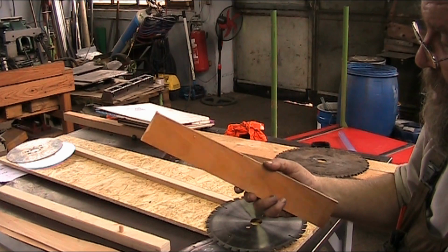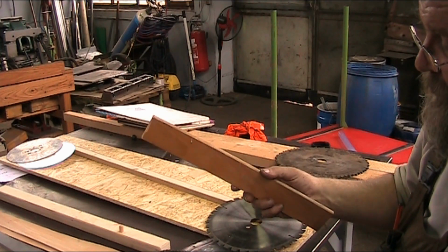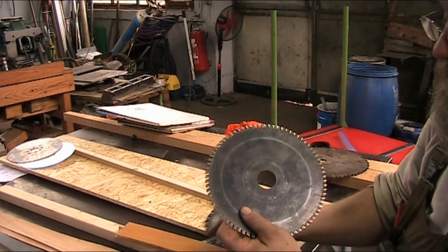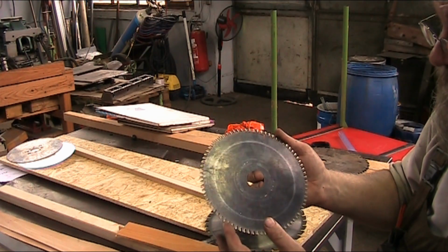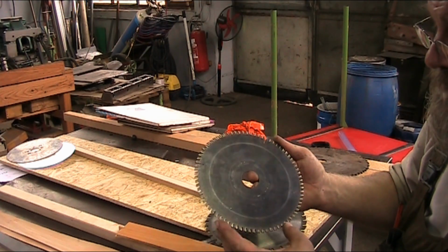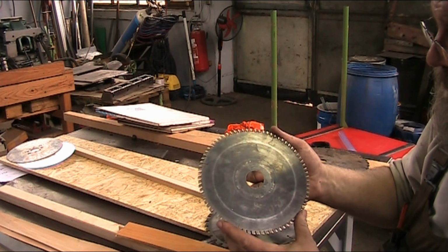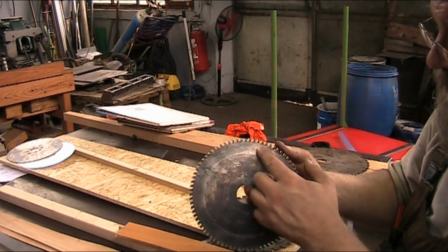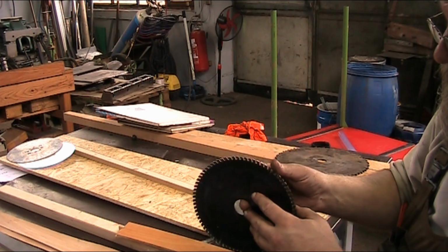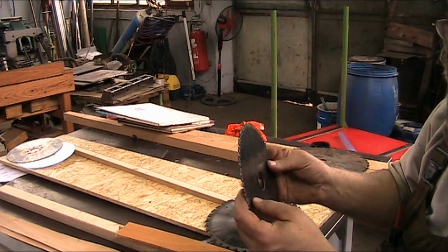So this is a beechwood plywood that has an arch to it, and this is the blade you'd want to use to cut this kind of stuff, where you have real close tooth separation. And then also you have a positive rake, and then you have an alternating grind. You can't see that.